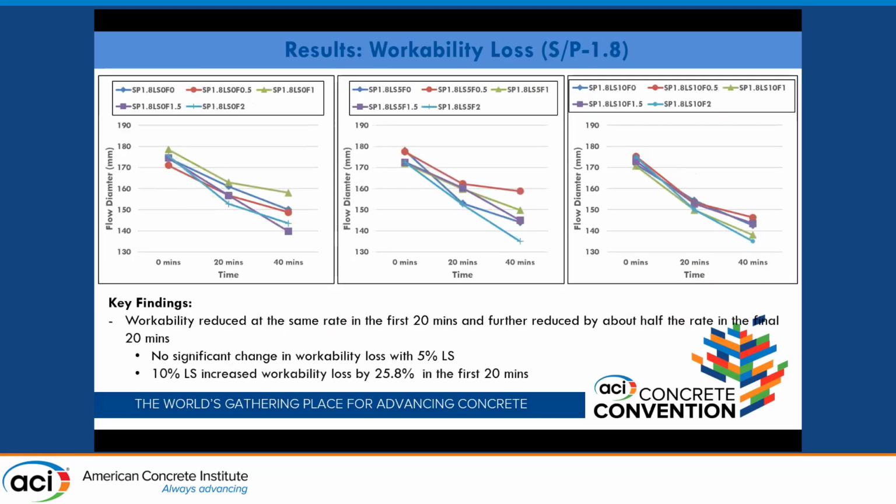This same trend was also seen at the sand to powder ratio of 1.8, however, we saw that 10% of limestone increased the workability loss by up to 25% in the first 20 minutes.